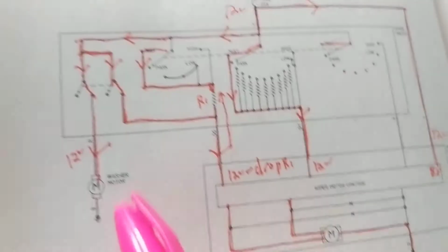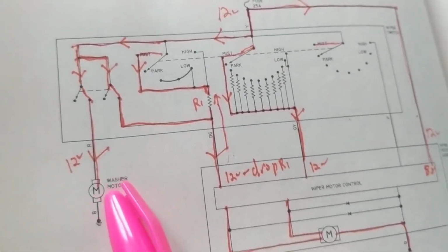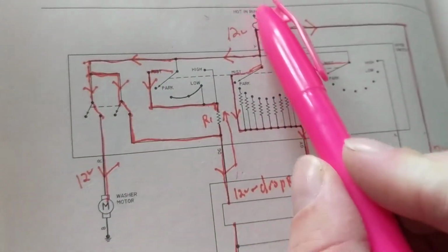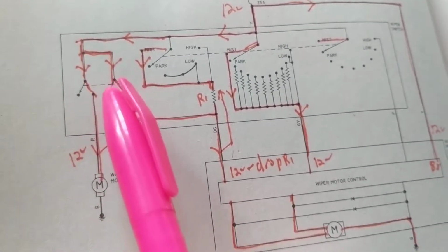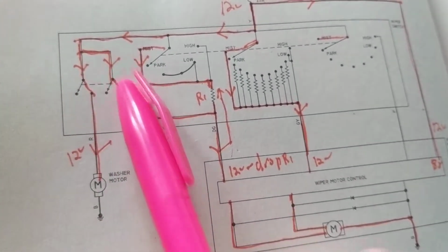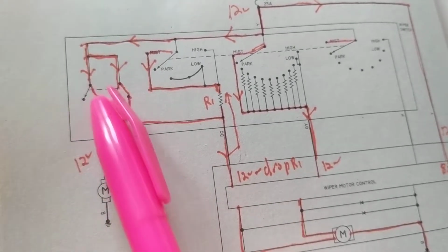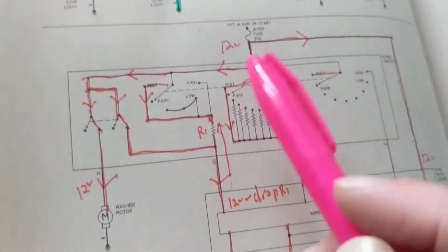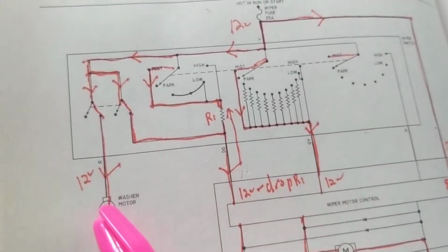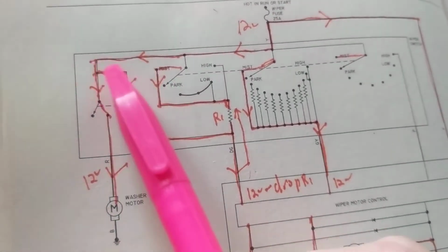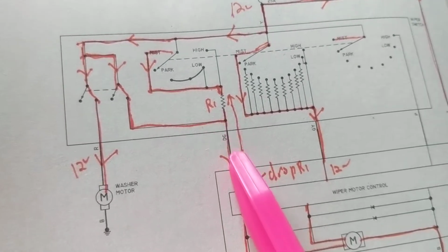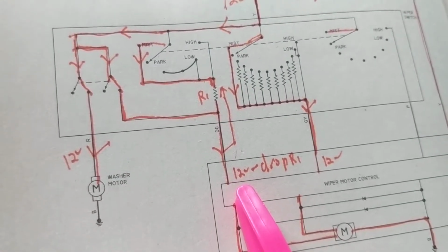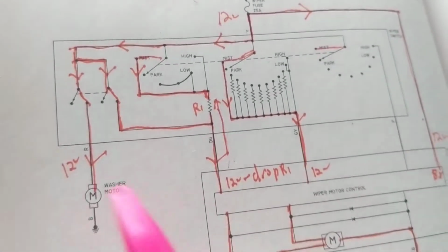So therefore, if I want to activate the washer motor, we just said we have current flowing through this from here. These are ganged together, like we said. Dotted lines means if I move this one, simultaneously, these move. Therefore, if 12 volts comes in here, the current also has another path to flow through this to give it 12 volts. So this has 12 volts.